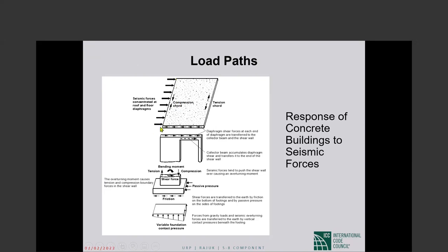And when the seismic forces act, the diaphragm is subject to compression, tension, and shears. Okay? Those shear forces are transferred to the frames and shear walls supporting the diaphragms. The frames and shear walls bring those forces down to the footings, which then transfer them down to the ground.